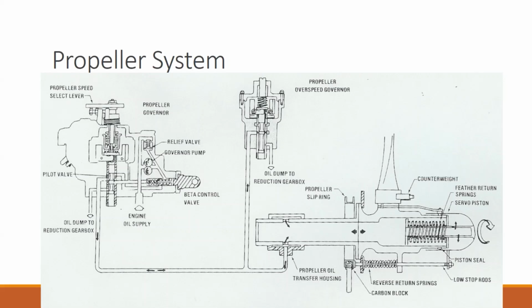But if it senses the power turbine spinning too fast, whether because the prop gets into an overspeed condition or for some reason you lose that link between the power turbine and the propeller, where the power turbine then can run away, that will reduce the fuel. That sends a command to the fuel control for the gas generator to reduce the amount of fuel going.